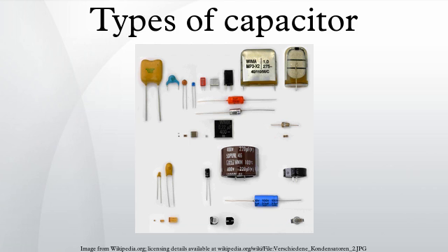For film capacitors, the permittivity changes with dielectric thickness and other mechanical parameters, so that the deviation from the theory has other reasons. Comparing the capacitors from the table with a supercapacitor, the highest energy density capacitor family. For this, the capacitor 25F/2.3 V in dimensions D x H equals 16 x 26 mm from the Maxwell HC series, compared with the electrolytic capacitor of approximately equal size in the table.